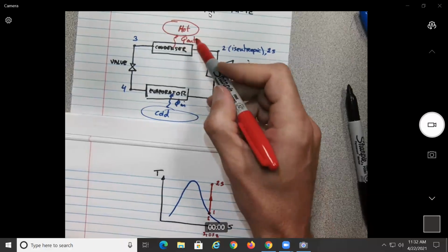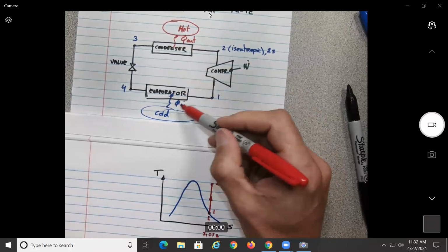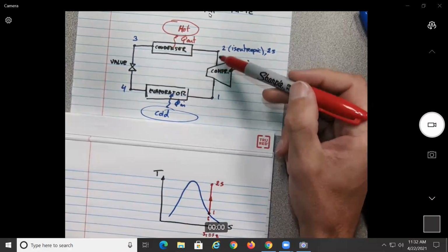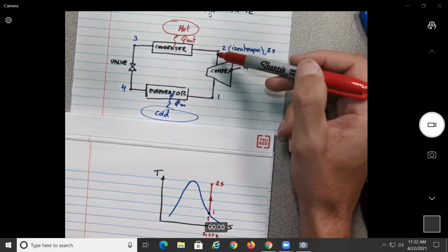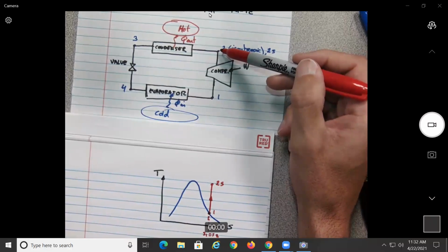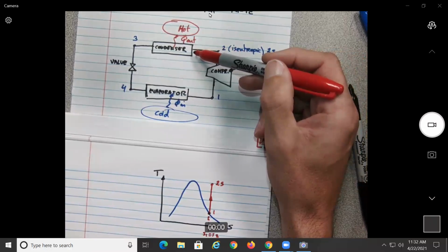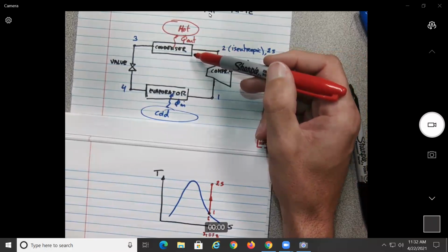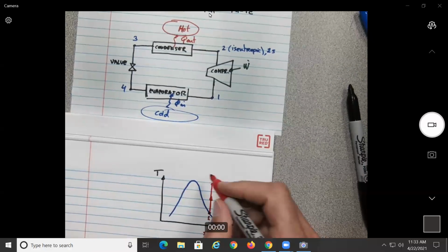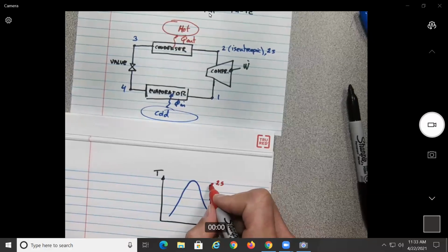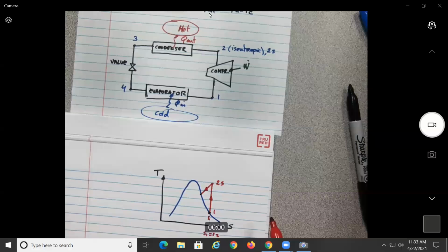So I'm starting from this point. The evaporator will come at the end. So it's when you cool over here. So we come here, point 2. Now we go through the condenser. So what are we doing? We are cooling, no? Okay, at constant pressure. So if you remember, this will have lines of constant pressure. We could say we go here through the line of constant pressure.